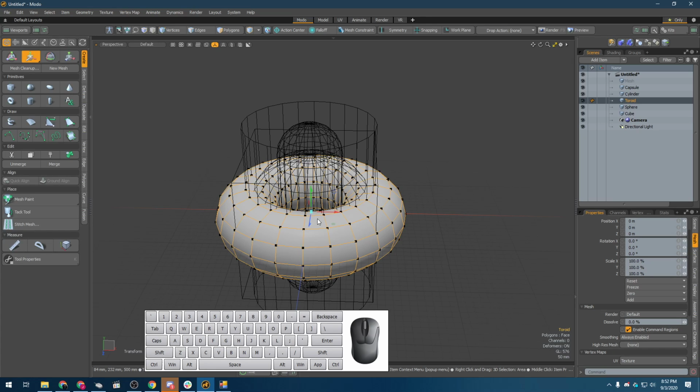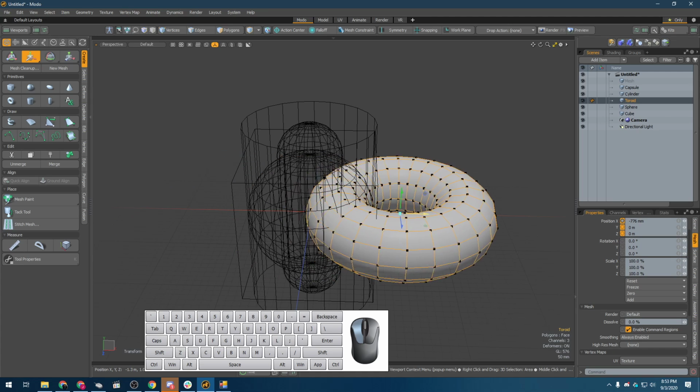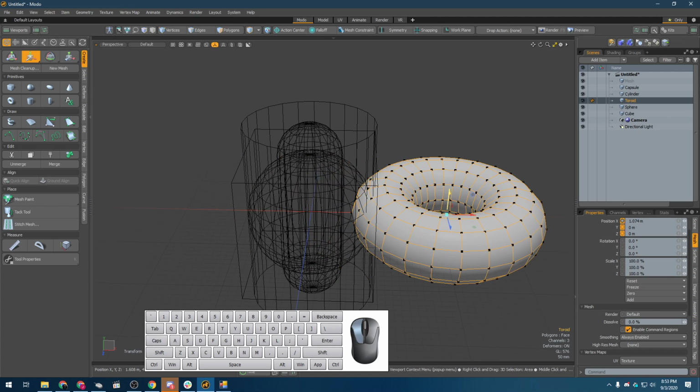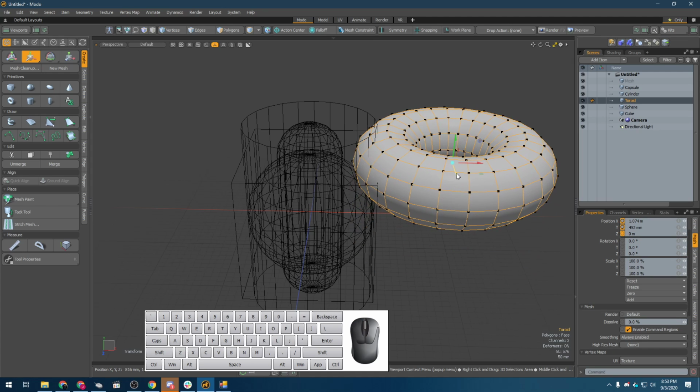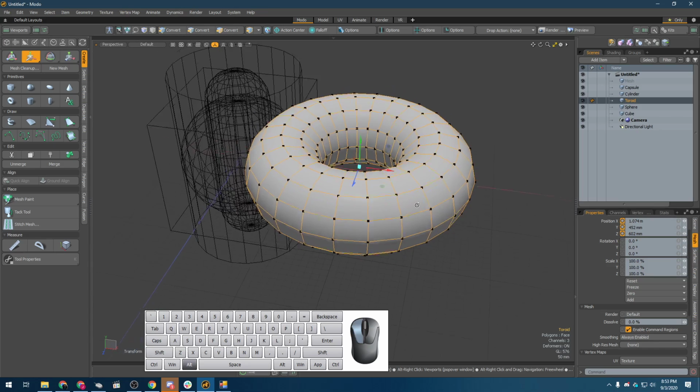When you have the tool active, we have what's called a transform manipulator over here in the middle of our object. That's basically the handles for using the tool in question, right? So with the move tool active, I'm just going to click on this red handlebar, click and drag, and it's going to move it in the direction of that arrow, right? If I grab this green handlebar, it's going to move it up and down. This blue handlebar is going to move it towards and away from the camera, okay, in the Z-axis.